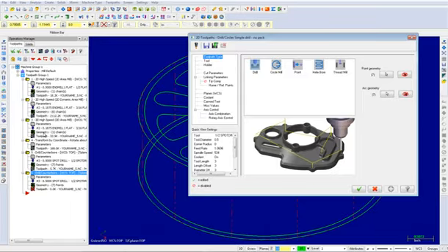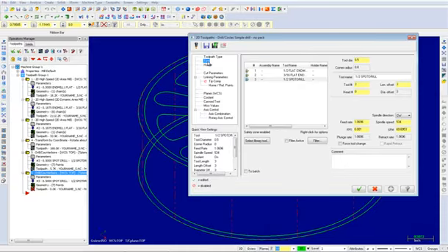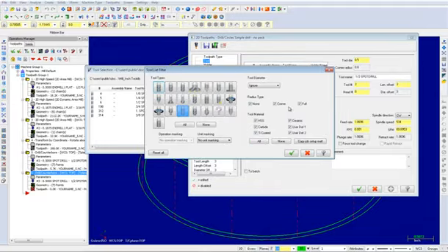Select the drill and from the tree view list, choose Tool. This time we will choose a 1/4 inch drill. To do this, click the Select Library Tool button and then choose Filter. From here, select None, choose the drill, and then put a tool diameter equal to 0.25. You can now press the OK button to exit the Tool List Filter dialog box.